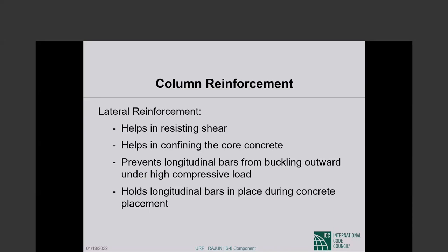The gain in strength, while substantial, is not huge, but the concrete now is, I would use the word, ductile. It can keep on carrying gravity loads while deforming laterally by quite an amount.